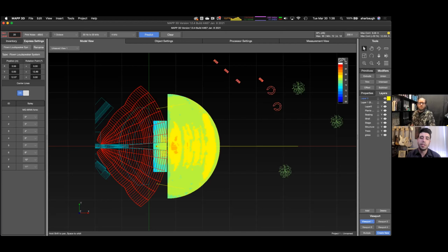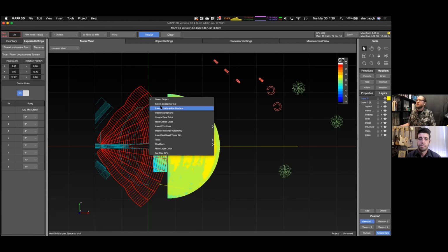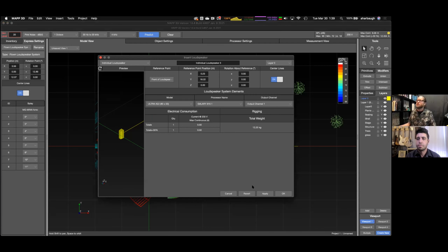Would it be easy to, for instance, look at a side view, and if you place an object in a top view somewhere along the Y axis, when you switch to the side view and move it around, would you stay to whatever Y point that you were snapped to before? Does that make sense? That's correct. Yep. So that is something I do often, is insert something where I know in plan view that loudspeaker needs to go.